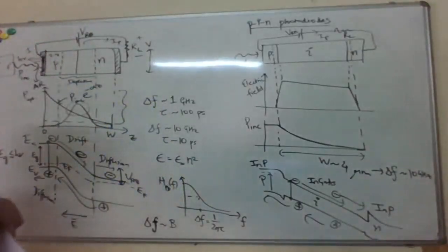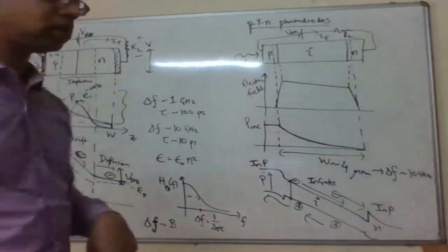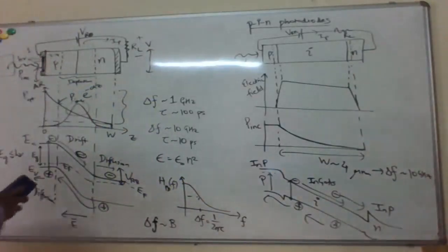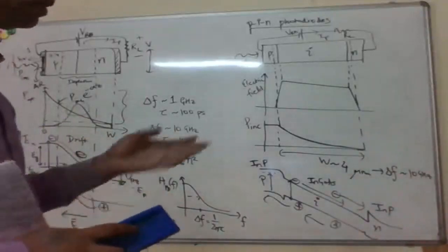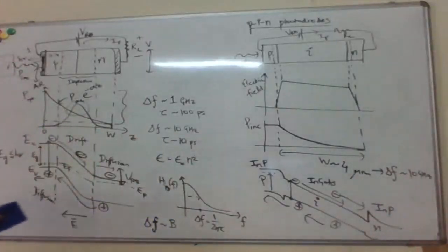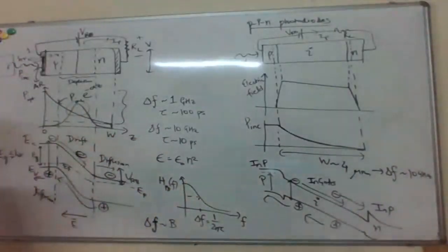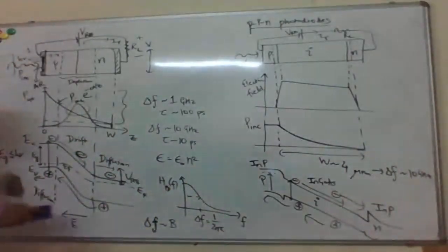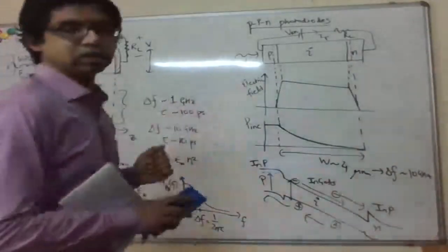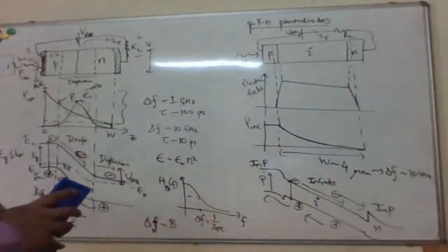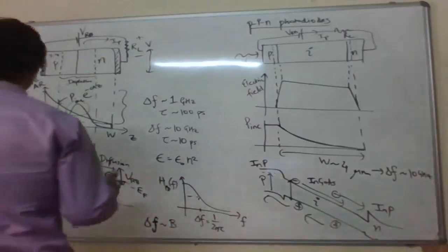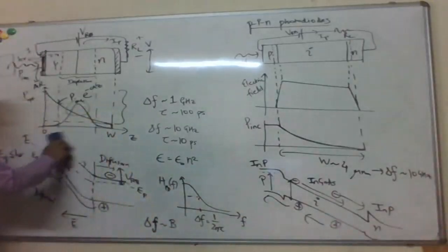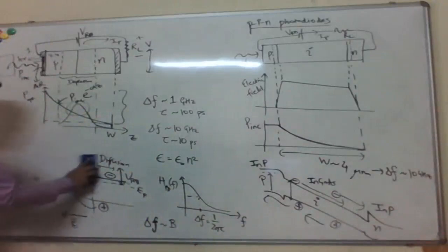But let's say if you want to detect much weaker signals, so much lower incident power, let's say now close to microwatts or maybe even into hundreds of nanowatts or below, then basically PIN photodiodes just don't have enough, the responsivity is not high enough, right? So that your signal is buried in the noise.